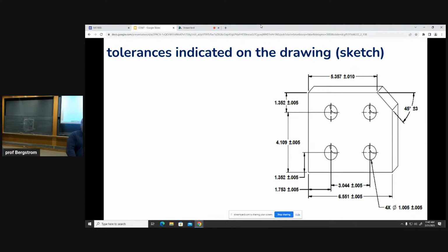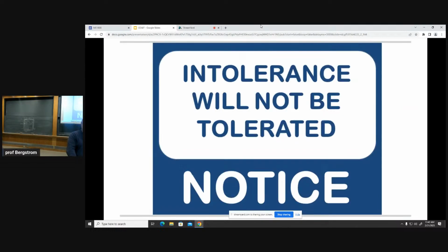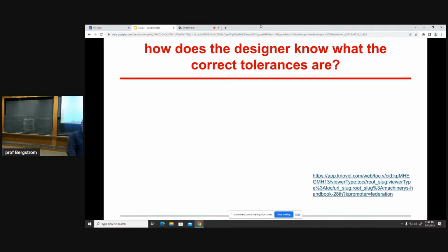Yep. I was gonna say, like, one example of the qualities. I actually learned in the cylinder that the piston was too big for my cylinder to fit in. So I was thinking, make the cylinder a bigger tolerance or make the piston a smaller tolerance. So that piston cylinder interaction is actually a functional tolerance. And if the one you made didn't work, it had something to do with the measurement or the setup of the machine, not the design. For sure.